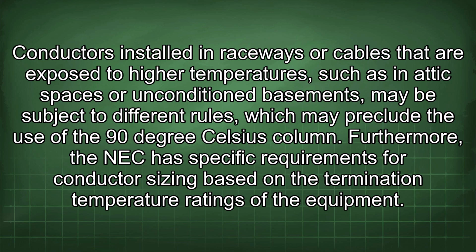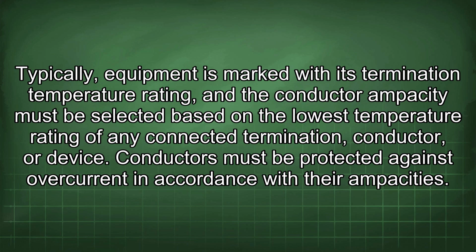Furthermore, the NEC has specific requirements for conductor sizing based on the termination temperature ratings of the equipment. Typically, equipment is marked with its termination temperature rating, and the conductor ampacity must be selected based on the lowest temperature rating of any connected termination, conductor, or device.